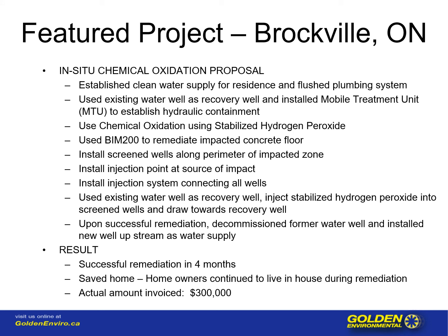We proposed an in-situ chemical oxidation process. First of all, our job was to establish a clean water supply for the residents and to flush the plumbing system. We used the existing water well as a recovery well and installed a mobile treatment unit only to establish hydraulic containment. Using their existing well, we were able to depress the water table in the exact area needed for this process. So we were not using the mobile treatment unit to remediate the site, but rather to establish hydraulic containment so that the contamination didn't move further off-site.